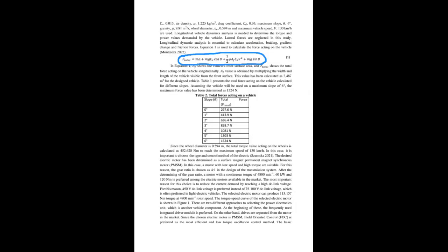Okay. Now we know my maximum torque. I need to select a motor for this operation. No, actually no. This torque value is very high. This continuous torque value is very high for a motor. We need a gear ratio. This is called a transmission. I select 4 to 1.